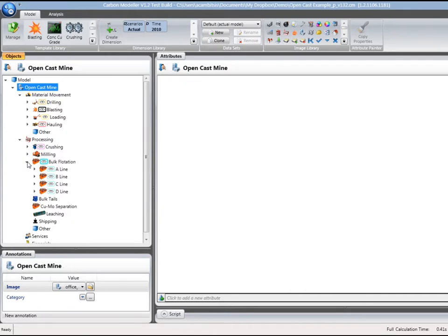Bulk flotation has the bulk lines modeled here, and under each bulk line is a recovery and cyclone overflow model. The recovery model models the behavior of each kinetic class. The cyclone overflow models the size fractions per float line accordingly. Each line has its own recovery and kinetic class submodels.